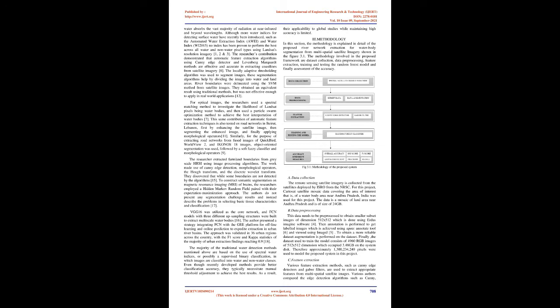The researchers' contribution demonstrated that automatic feature extraction algorithms using Canny edge detector and Levenberg-Marquardt methods are effective and accurate in extracting coastlines from satellite imagery. The locally adaptive thresholding algorithm was used to segment images. These segmentation algorithms help by dividing the image into water and land areas.